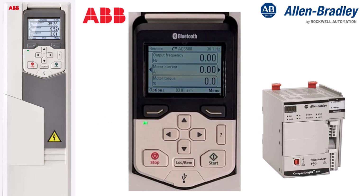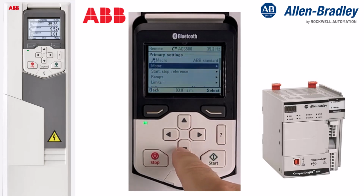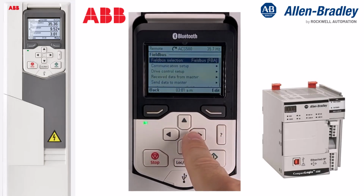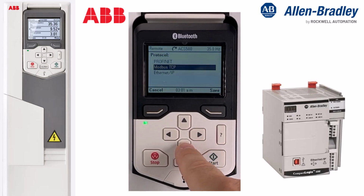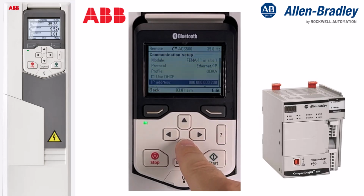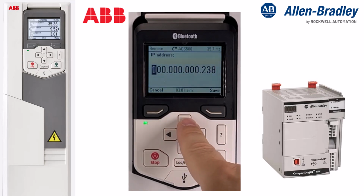First thing we're going to do on the drive is click Menu, go to Primary Settings, and then scroll down to look for Field Bus. Once we do that, we'll verify the FBA is selected, and then go down to Communication Setup and go to Protocol, choose Ethernet IP at the bottom of the list, save. Then verify the profile is ODVA, and then we'll come down to the IP address and type in the IP address as needed for your particular network.